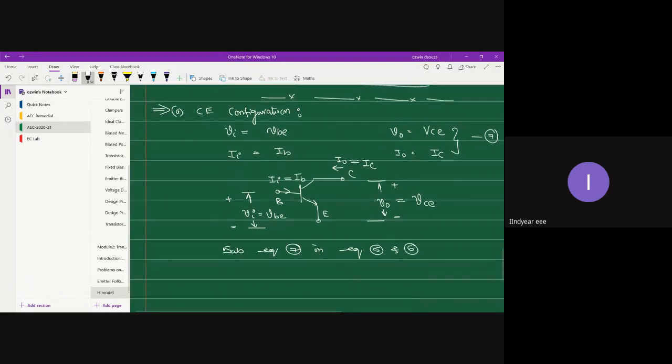So I have my input voltage, which is VB, and then HI. I'll write HI as it is. Since I'm dealing with common emitter configuration, I will write E. Wherever you have an H parameter, you introduce E: HI becomes HIE, HF becomes HFE, and so on.